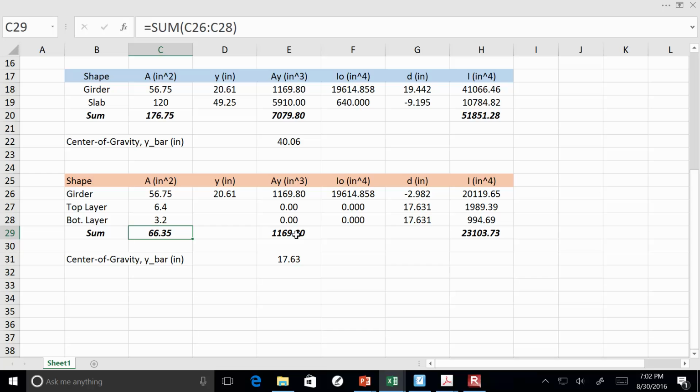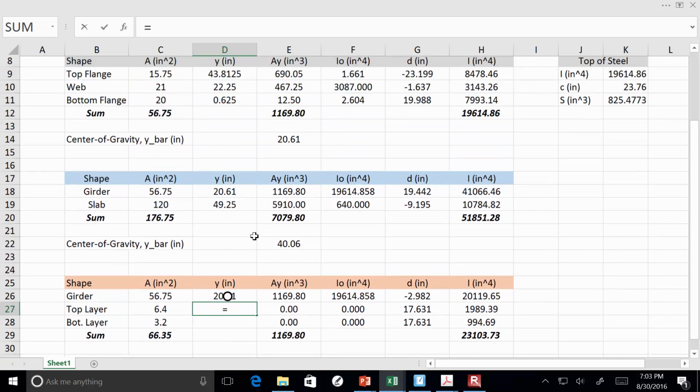Now, why would I do that? Well, where is that top layer of rebar? It's 2.5 inches down. How did I come up with that 2.5 inches? That's that cover requirement. Remember that? Remember, for de-icing salts in this area, cover requirement. Now, you could make the argument, well, wait a minute. Technically, the center of that bar should actually be a little bit lower because it's got a radius, but close enough for government work. All right. So we're going to go. Let me scroll up here a little bit.